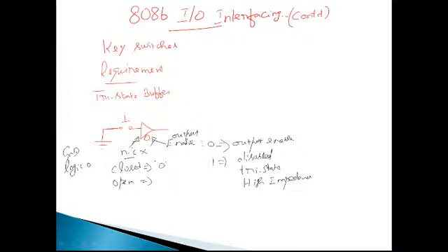So in order to make sure that when the switch is not closed, logic 1 is applied to the input, how do I do that? Very simple. I can connect a pull-up resistor with this particular thing, like this. Normally this will be around 4.7 kilo ohms, and this terminal can be connected to the power supply VCC.